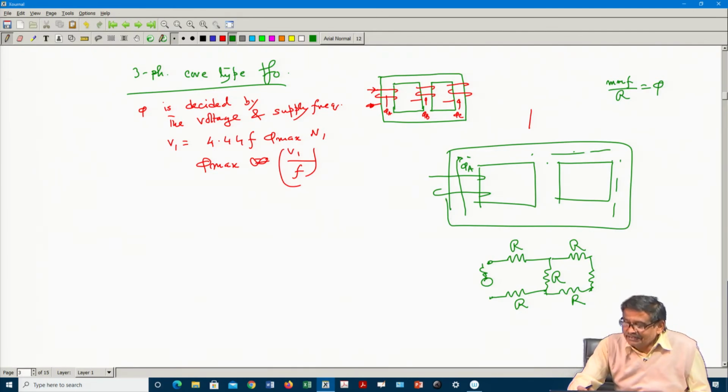In fact, reluctance seen by this coil will be less. Therefore, the magnetizing current drawn by the A, B, C phases will not be balanced. People do not mind that. After all, it is the magnetizing current which is less. I have chosen very good magnetic material, and 3-core transformers are very simple and occupy less space. You compromise with that; it is accepted, nothing like that.